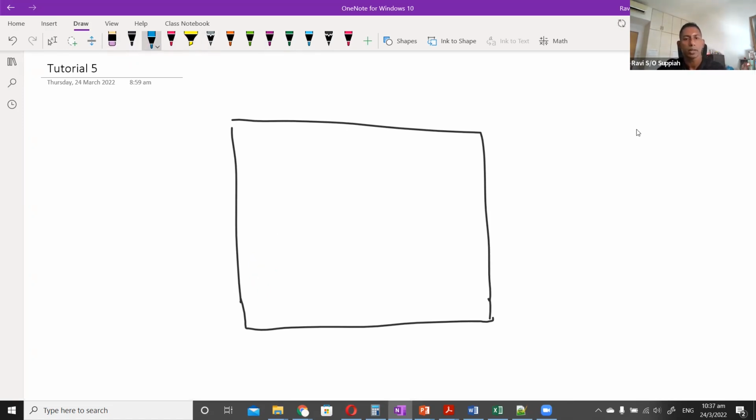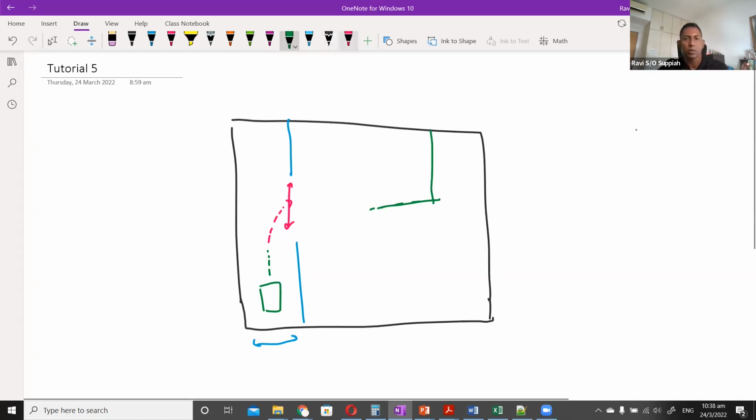When you arrange your walls, try to keep a bigger space for your robot, like a gap. Try to arrange something like this where you have a bigger gap between the walls, and you have an opening. When you start your robot, it must be able to maneuver, and using the LiDAR data it must be able to detect that there is a gap over here. So you need to look out for the gaps, so you know that this is where I should go. Once I reach here, maybe you can have another setup, something like this. Once the robot comes here, it will know that I have some space here, and then I need to maneuver and explore.